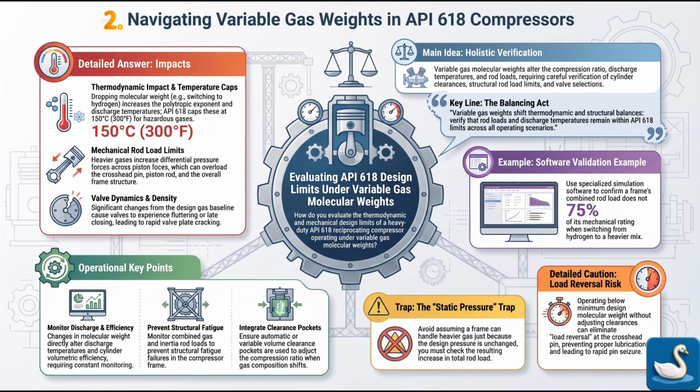And what is the mechanical reality behind that 150 degrees Celsius limit? Why is 150 degrees the absolute ceiling? Steel doesn't melt at 150 degrees. Steel doesn't, but the non-metallic wear components absolutely do. Exceeding that temperature degrades the internal Teflon or PTFE piston rings and rider bands.